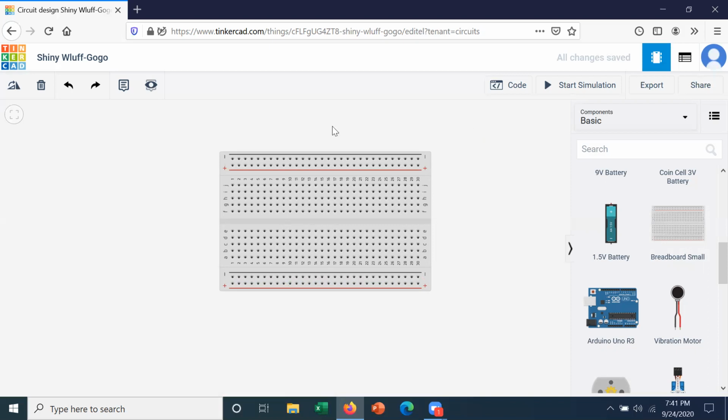In the body of the proto board here, we have columns. And notice if I hover over one of them, all 5 of the connections in the columns light up, meaning they're all tied together. If I go over to the next one, they all light up and so forth. These things are labeled. Down starts here A, B, C, D, E, like the seats of an airplane, I guess.